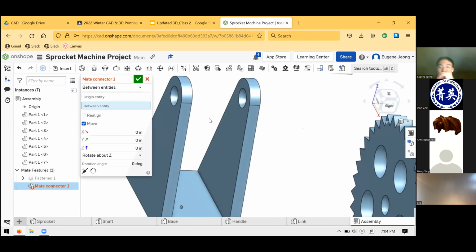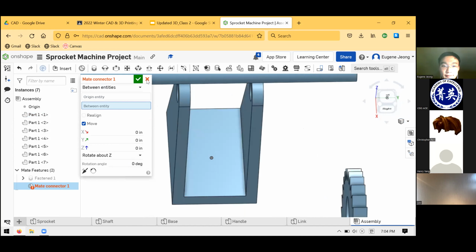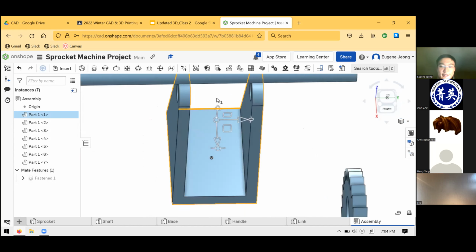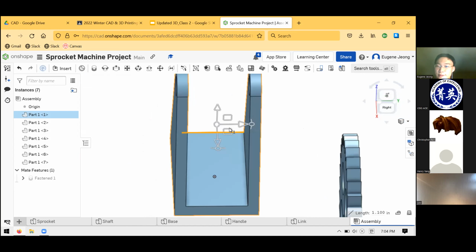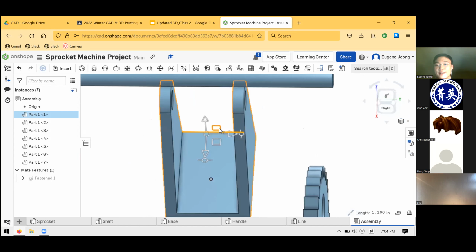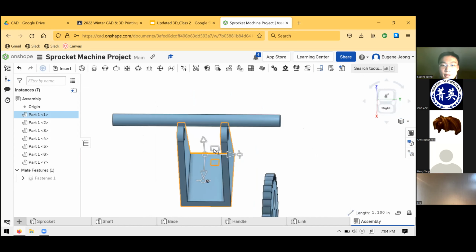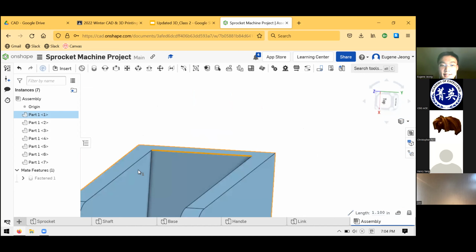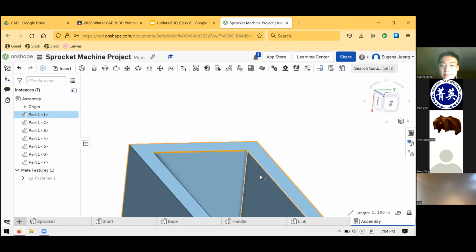All right, well, the exact way these mate connector things work is perhaps escaping me for the moment, but don't worry. Take a quick moment to figure out what the distance is between your base. We're just going to manually create the offset, and you can worry about the mate connectors later. Between where and where? If you just click on this part of your base, the distance between the insides of each of these standing up parts.